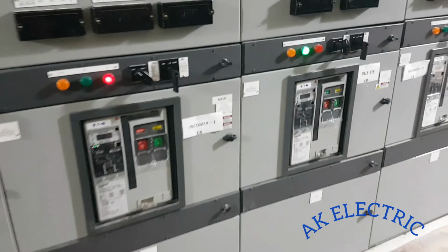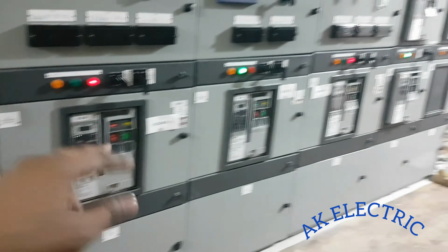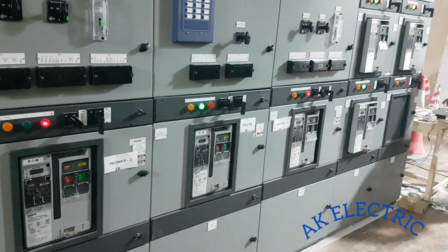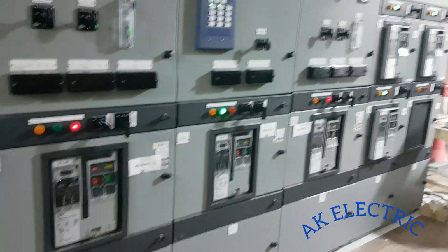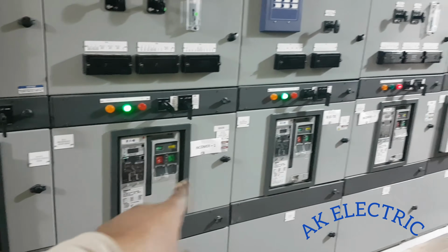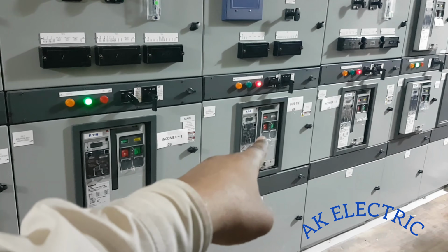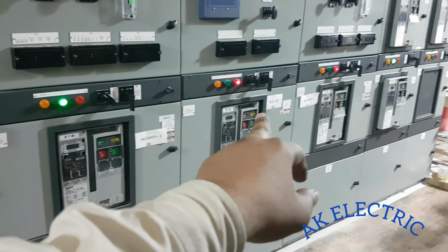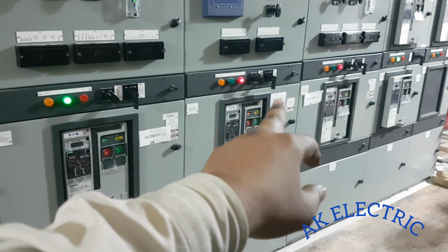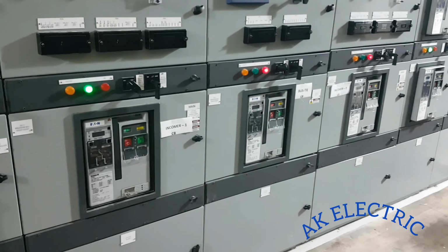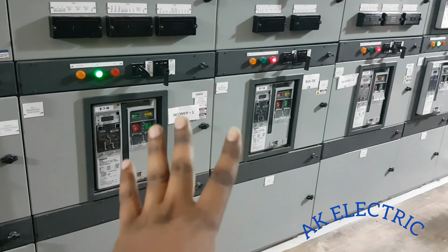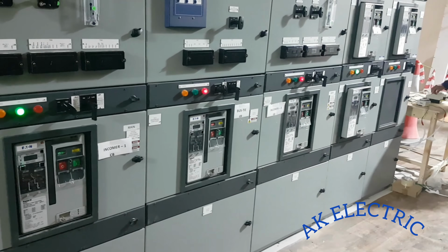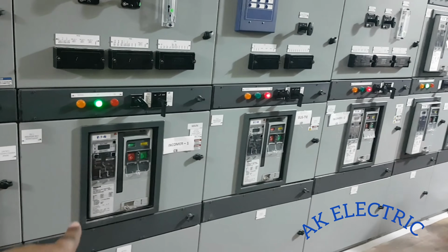So now we will make the power loss for incomer 1 by switching off the incomer 1 AC supply. Now incomer 1 AC voltage is off, this breaker will trip and the tie breaker will close automatically. Now incomer 2 supply will come to tie, and through this tie incomer 1 is energized. This is automatically done. This is ATS. Now incomer 1 supply is given on again.